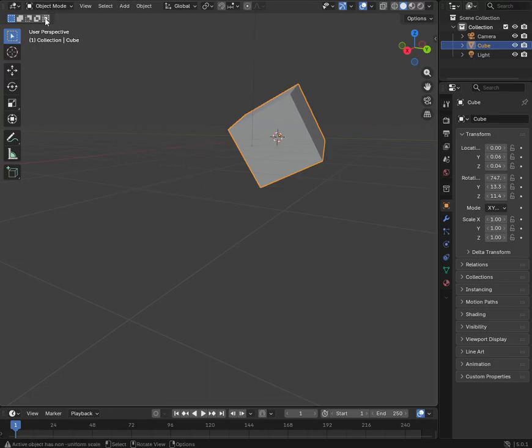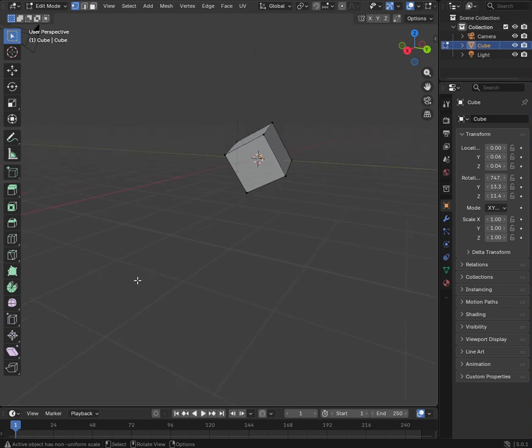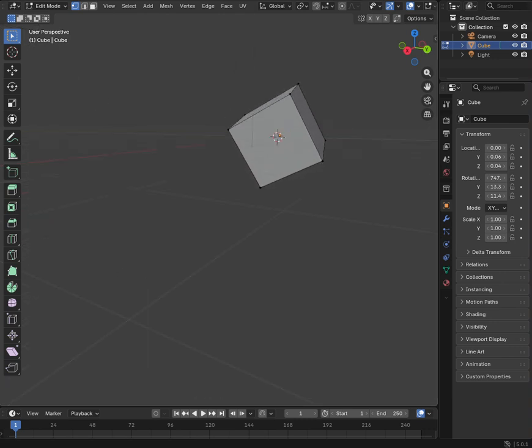Then this is something about selection in the object mode. Now if I talk about edit mode, in the edit mode there are 3 ways to select things. You can either select individual vertices, lines or planes. In order to switch between the 3, you can click the buttons at the bottom likewise.